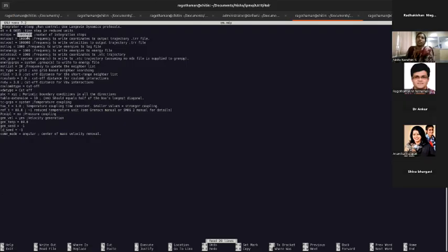So this is the time steps and the total number of time steps that I was talking about. Here it is like 1 crore steps in order to get the simulation that I've shown you, and I've written the files out for every 1 lakh steps. Even when visualizing, if you don't want to visualize the entire trajectory, we can skip some of the files using the skip command when you convert the XTC file into PDB, only for visualization purposes. But when you want to analyze, you should use the entire trajectory so you can get complete information about the system. You can also plot the RMSD and RMSF plots, which help us study how the system changes during the overall process.